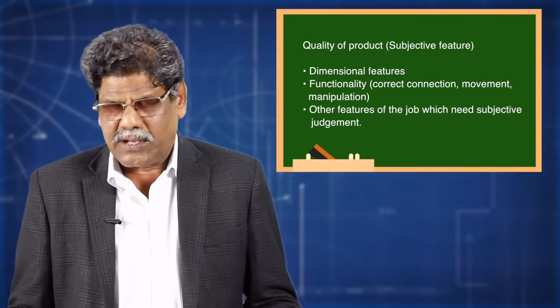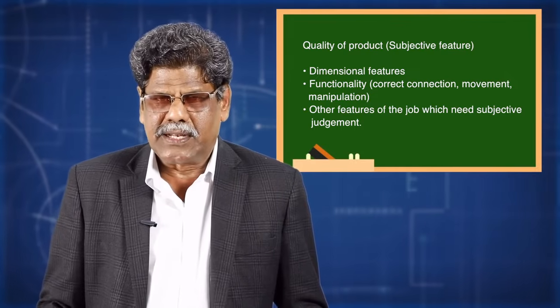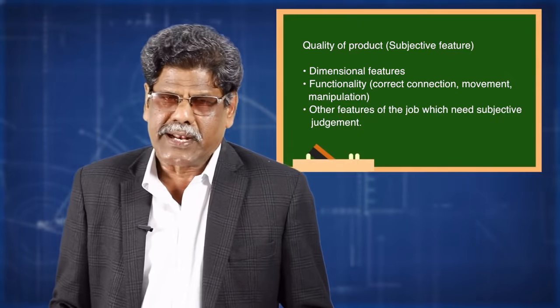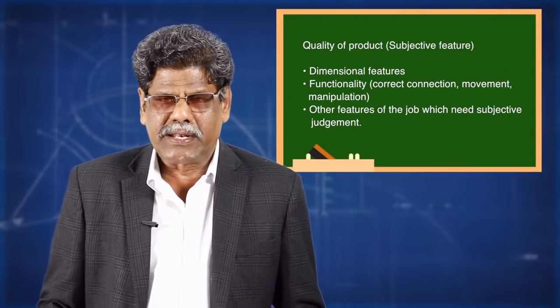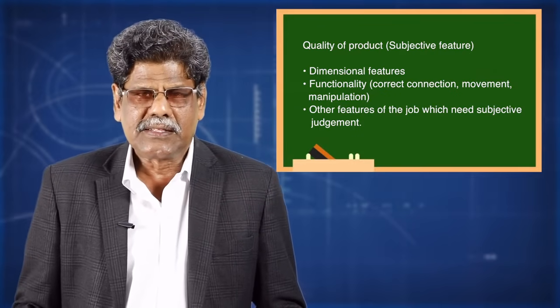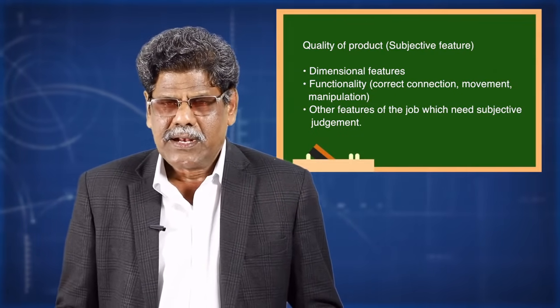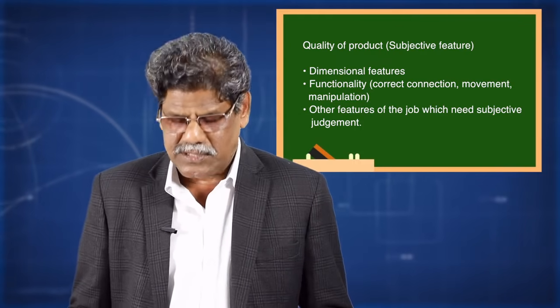procedure, he has to connect by the correct method. That is, suppose if he has to connect an ammeter or voltmeter, he has to connect the ammeter in series, the voltmeter in parallel. Like this, the correct connection he has to give.